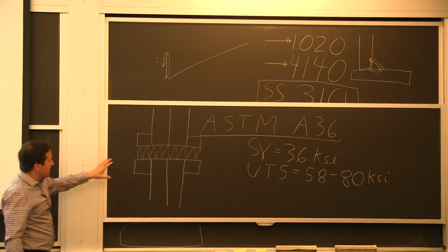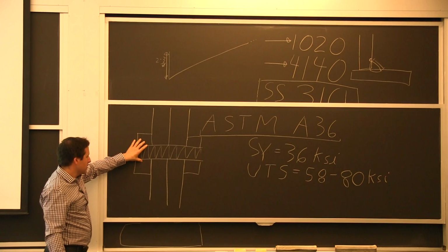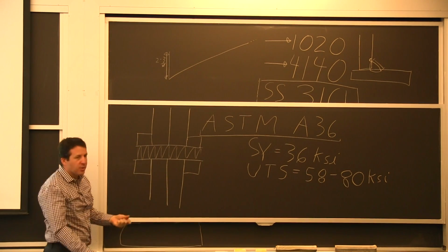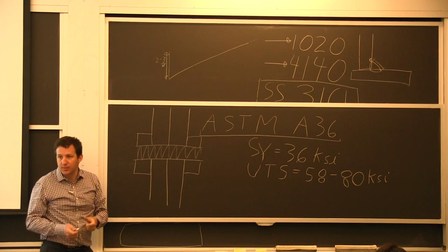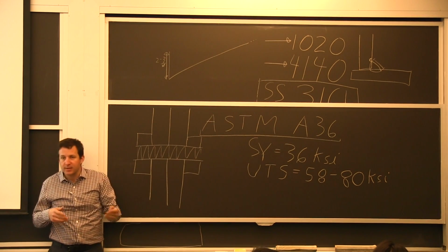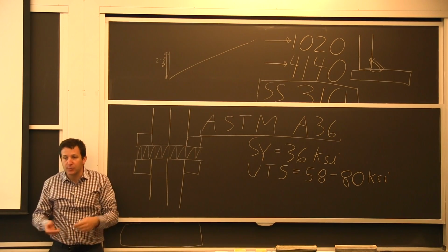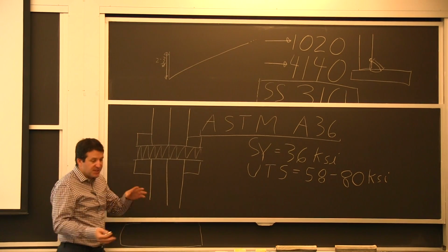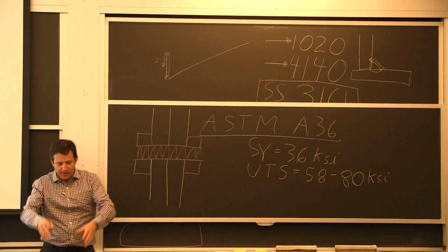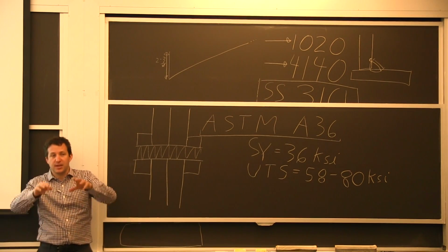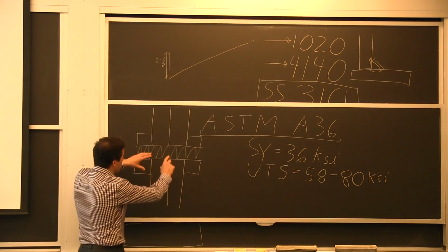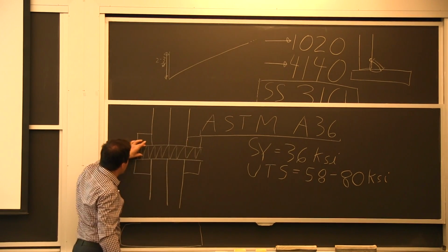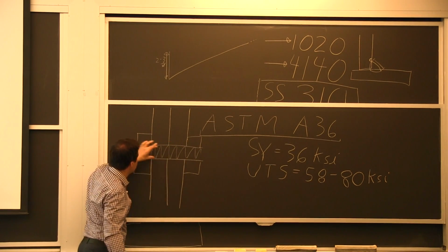If I want this assembly to be resistant to any cyclic load, this happens in pipe connections, for example. If you have a water line, there's always going to be variation when valves open and close, and seasonal variation from ground settlement going up and down, or if it's a big pipe, you're going to want to avoid having these variations go into the bolt.